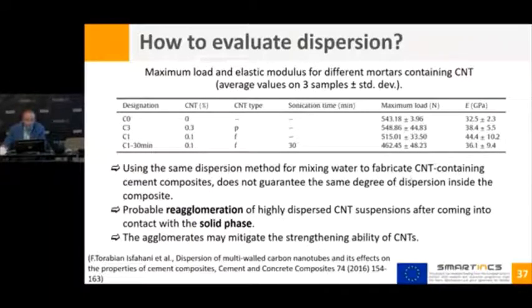But also what they observed is that once you correctly disperse the carbon nanotubes into water, the work is not finished, because then you have to consider that you will add the cement powder to your dispersion, and you have to verify that the solid phase addition, so the cement powder addition, will not perturb your system, and that you will also have in the hardened cementitious material a correct dispersion of the carbon nanotubes.